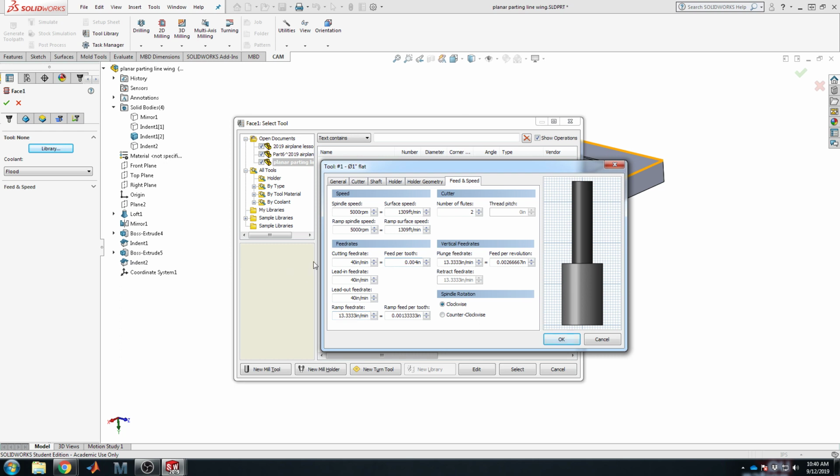And all of these numbers kind of come out in combination with RPM to generate a feed per tooth. Basically this is the depth of cut each individual edge will be taking as it's progressing through material at 40 inches per minute and spinning at 5,000 RPM. Now these are actually more like, what might you call it, convex slices, the little crescent moon shaped slices. So the depth isn't exactly constant all the way through, but the chip load, the feed per tooth, is really kind of what you're looking at. So okay, 40 inches per minute sounds pretty good.